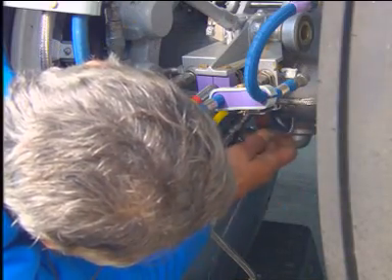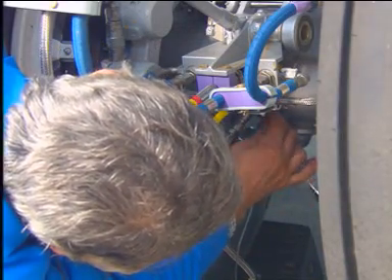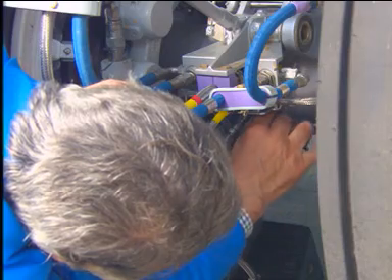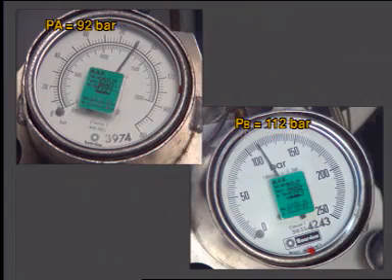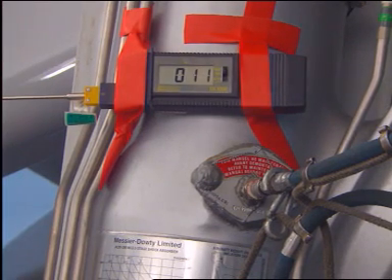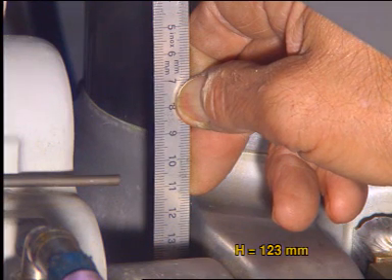And close the bottom charging valve. Wait 10 minutes and make sure that the pressure condition between the two chambers is fulfilled. The pressure condition is fulfilled. The nitrogen pressure being released, read and write down the temperature again, as well as the dimension H.